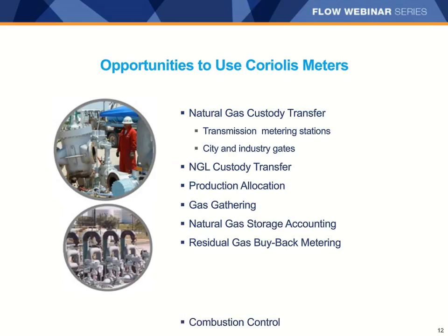By using direct mass flow measurement as an input to the air-fuel ratio control on a compressor or a fire heater, it is possible to use fuel gas with highly variable composition and still maintain huge reductions in emissions and fuel consumption. This can add a secondary benefit of reduced energy costs by potentially eliminating the need to install electric or dual-fuel compression engines that would otherwise be required to stay below emission caps.